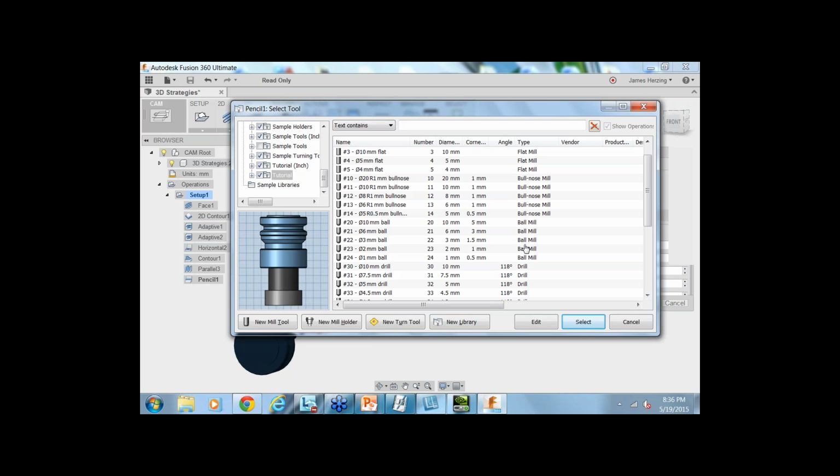Breaking down those operations, so a 3 and a 2 and a 1. Typically, the smallest tool is the one that's most required for the operation to get the radius. But depending on the operation, let's say we have a bottom radius of 4mm, we can easily get away with 2. So you want to calculate the largest tool you can fit into the profile you're machining.